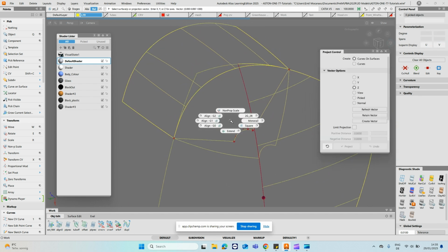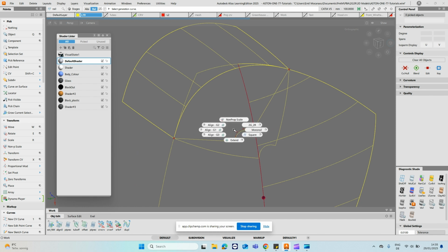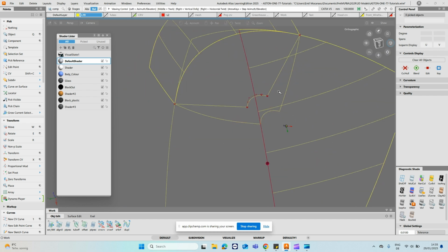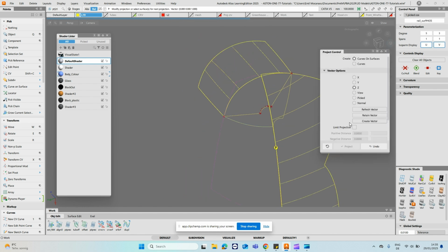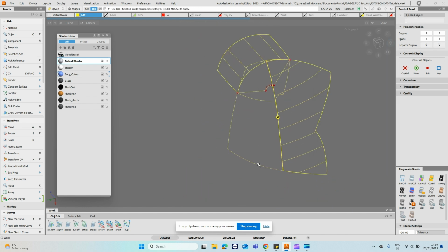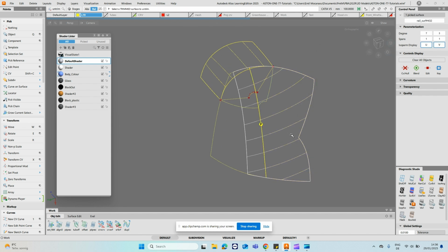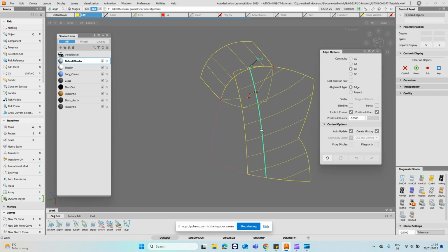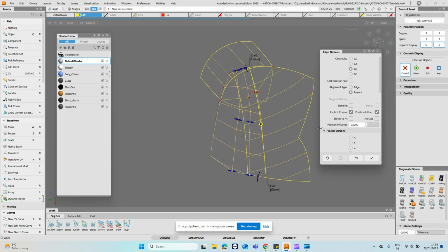Let's try and get that closed up. So my go-to method would be a bi-rail, but because we don't have that connection there, it might not work as I thought. So we can untrim this, delete that curved surface, and now we can project the line this surface onto this one in the normal direction.